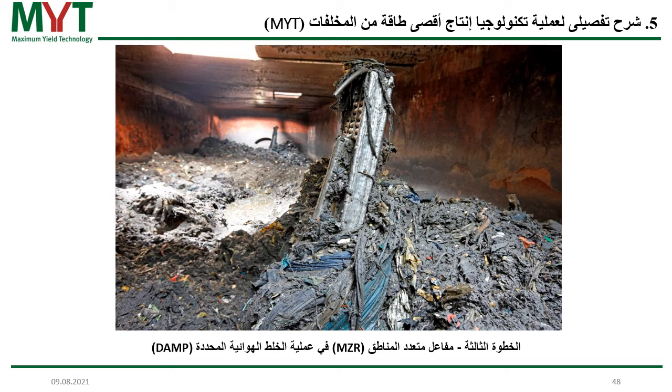This is a hydrolysis. Here it's the preparation for biogas production. The waste is mixed with the process water and turned around. The aim here is also to reduce the pollutant content of the waste. By applying the process water, the salts are also washed out of the waste or reduced. So this is why we can create a very high quality RDF, because the pollutant content is reduced and can also be controlled by washing.